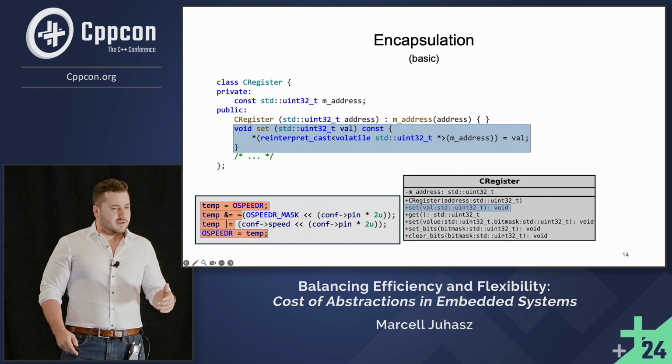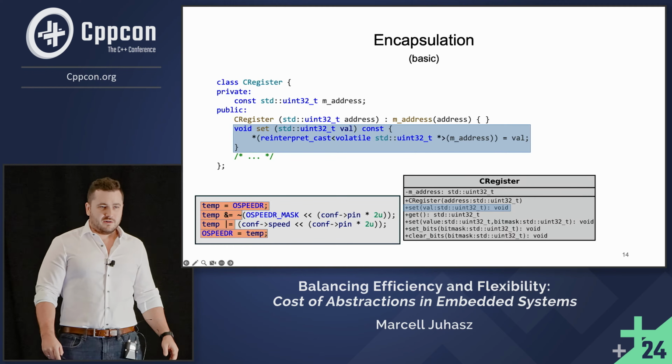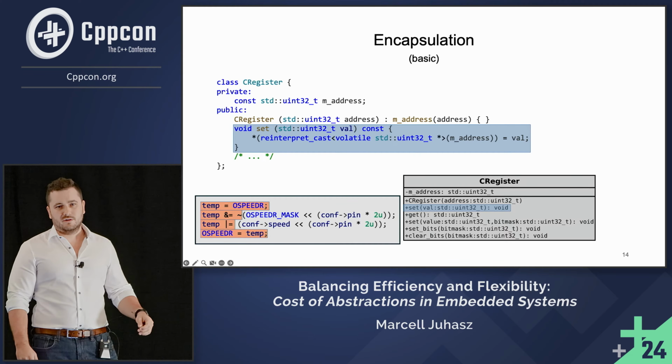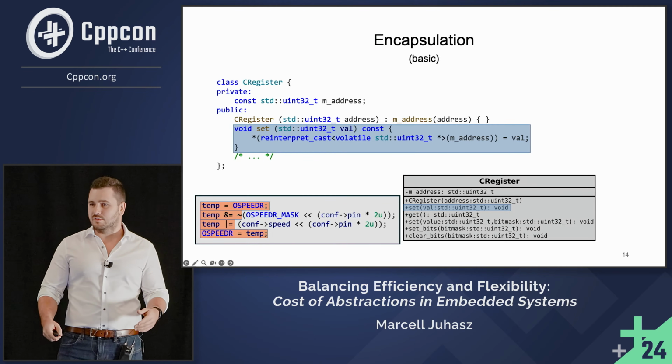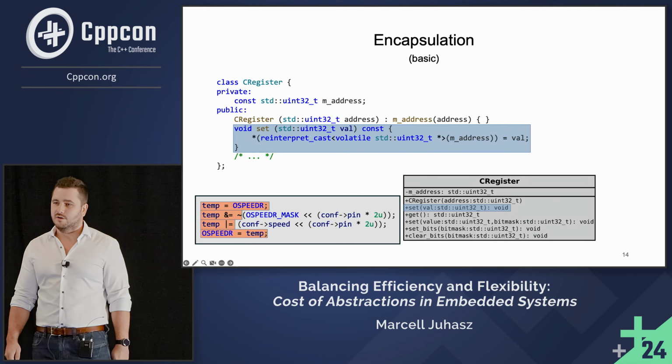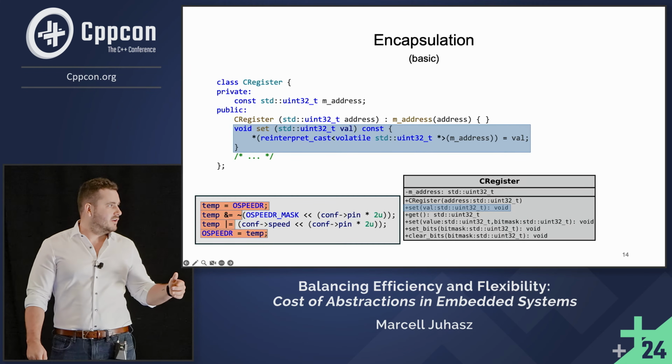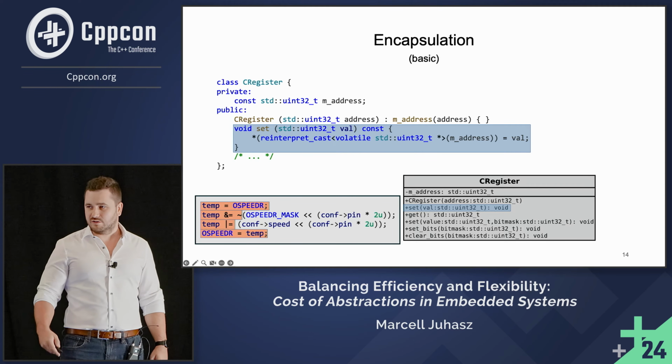So this is the class that implements the generic register behavior. It provides member functions that allow us to interact with every register in a common way. For example, setting the whole register, reading the register, setting only parts of the register selected by a bit mask, and so on.